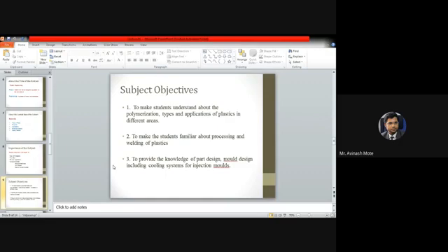Okay, what is the mold? Mold is that particular structure where there are some cavities, and those cavities are a replica of the product. So whatever type of product you want, you will pour molten material in, and when that molten material is poured into those cavities, it will form a similar type of product, whatever the size or shape of the cavity is. Okay, that structure is called a mold. So here also in a similar way, for manufacturing plastic, we need to have molds.